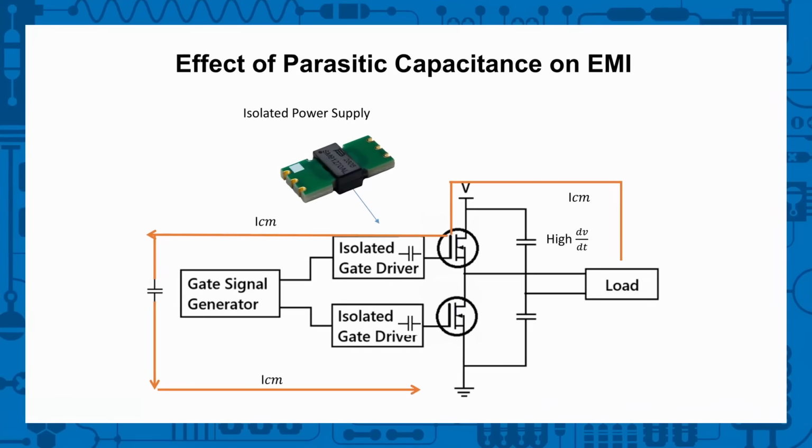And what are the parasitics like in those planar transformers, and how does that impact these isolated gate driver circuits? The parasitics can be, I suppose, when you have a concentric wound transformer, you do have a very wide tolerance, even in production, in some values like parasitics, because the parasitics depend on the gap between the primary and the secondary, and you're going to have a kind of wound structure on top of tape. There could be air gaps inside there, things like that.